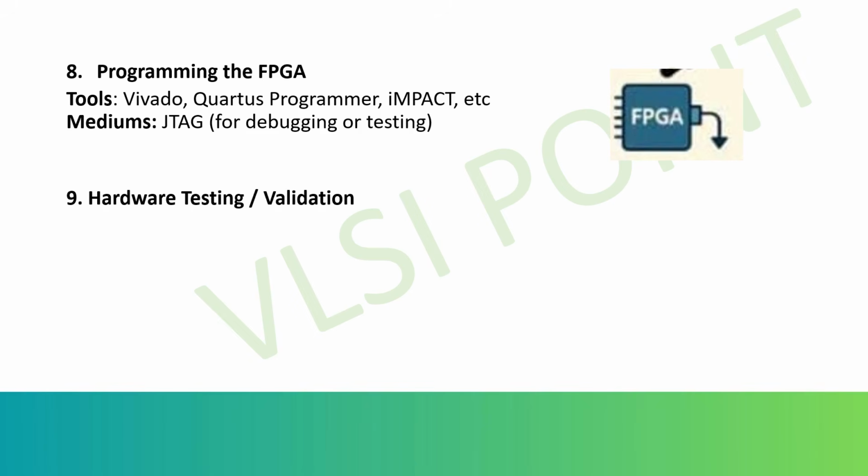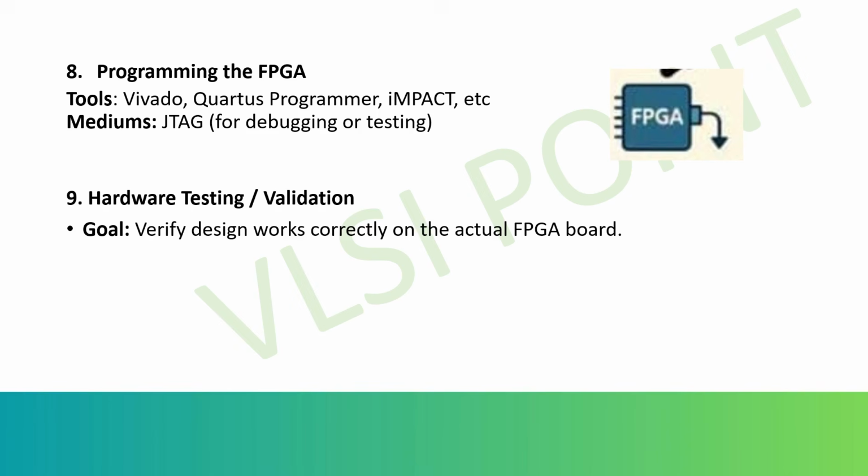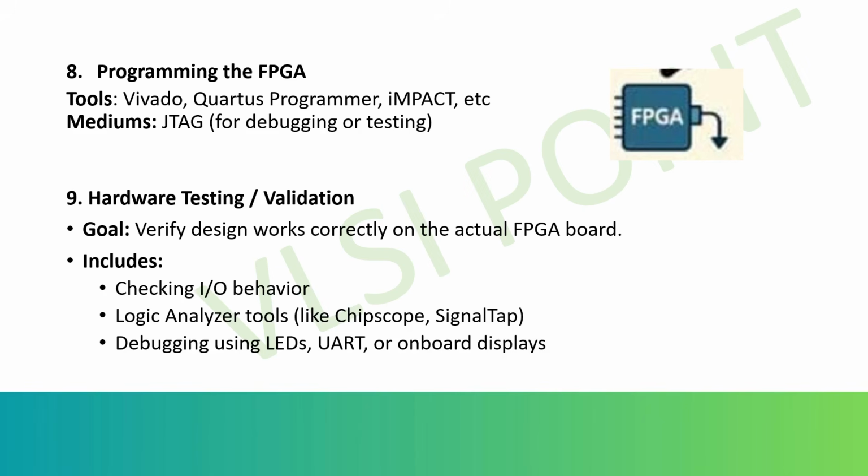And finally, there will be hardware testing and validation. So now you can test on a real FPGA board and verify the output with LEDs, UART, or logic analyzers like ChipScope or SignalTap. So note one point here, guys. For simulation, we need design code and test bench. But for synthesis, we need your design code and XDC file where we define all the clocks, and where you will check your output, either on LEDs or using switches.